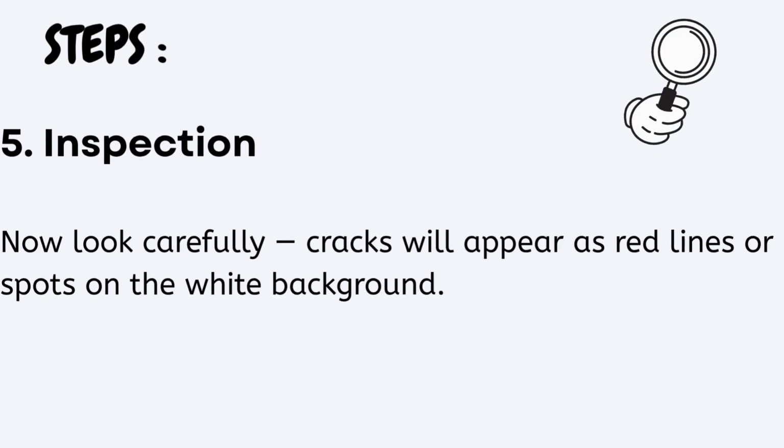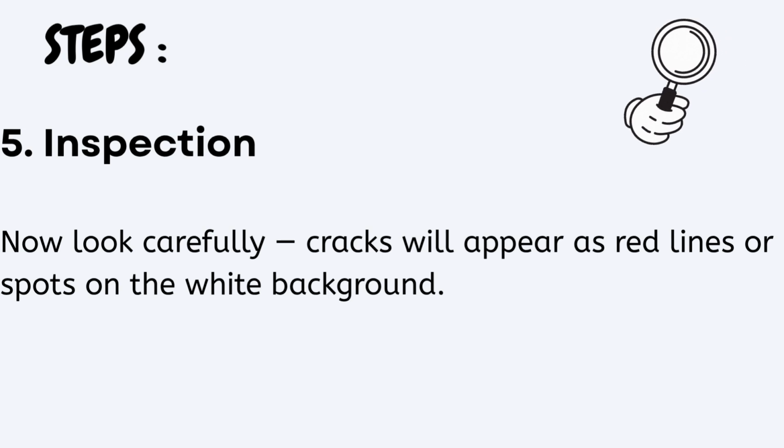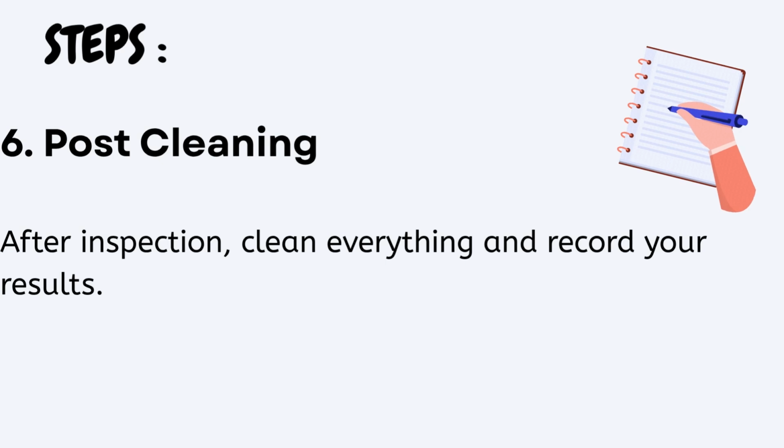5. Check the surface. Now look carefully, cracks will appear as red lines or spots on the white background. 6. Clean again. After inspection, clean everything and record your results.